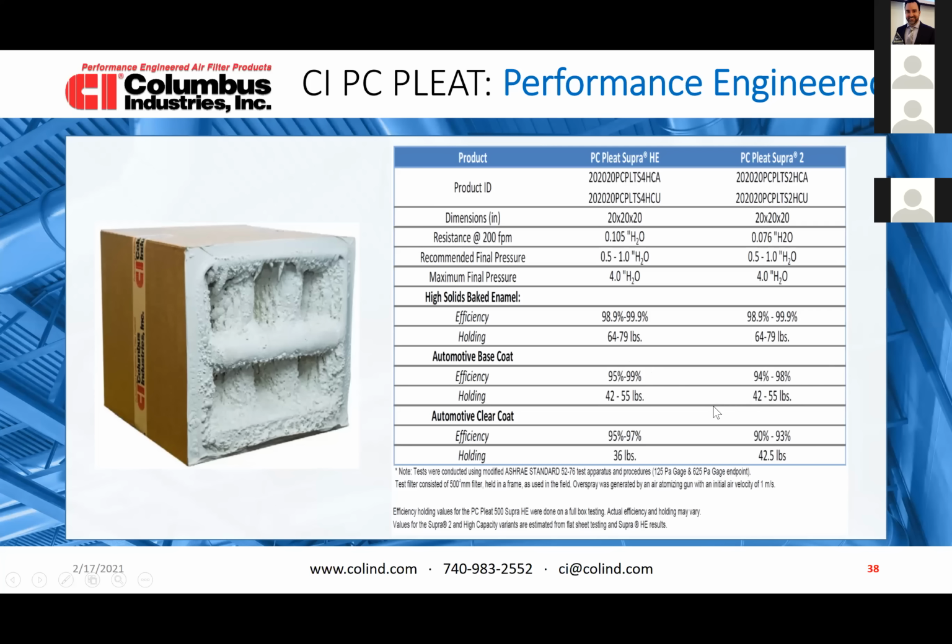When does it become necessary to use this type of filter? For example, when clear coat is required. If you're going to be at 96%, and I use 96% because that's the level the OEMs were claiming when they were selling their turnkey operations with this kind of filtration concept, basically, if you go with the Supra 2, you're not going to get your efficiencies. Here, as you can see, you can hold more, but before you get to that point, you're letting out a lot of paint, like we talked about earlier.